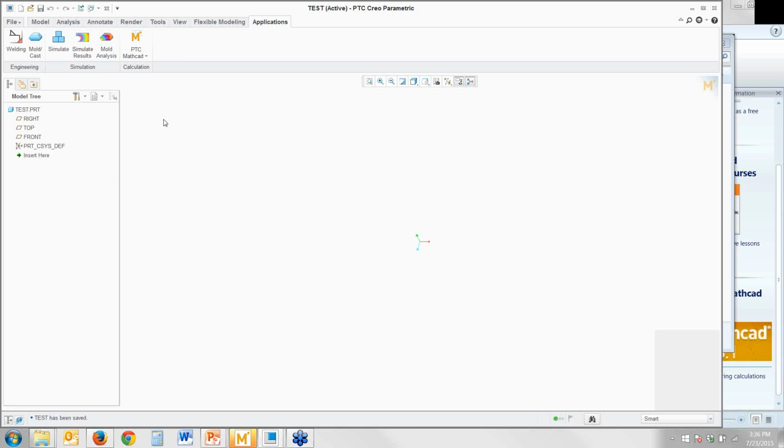It will leave your Creo design at the last known parameter or input values that it received from Mathcad. It will not fail immediately. It'll just leave it at that last known design state. Then if you want to update any changes, you would have to embed the Mathcad worksheet and run the changes through Mathcad, if it's going to be a mathematical change that you make through Mathcad.